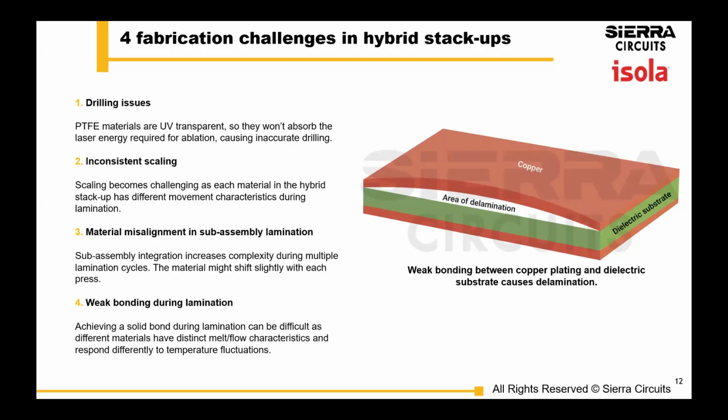Other materials would have a different process to roughen the surface, either for solder mask or for plating the inside of the hole wall. So in hybrid stack-ups, the manufacturer is considering the best between those two materials in terms of the drills, feeds and speeds, as well as the plasma process inside those vias to roughen up the material prior to seeding.